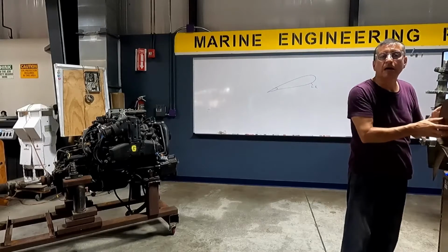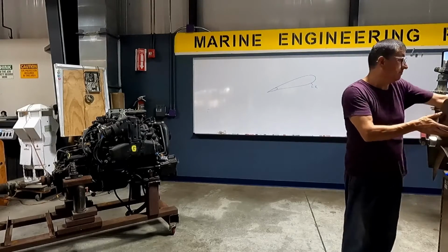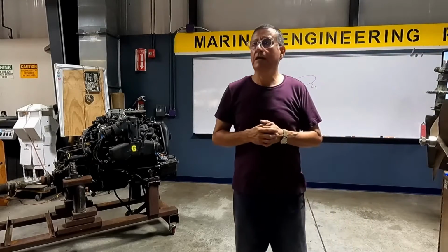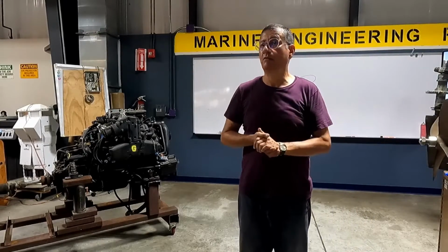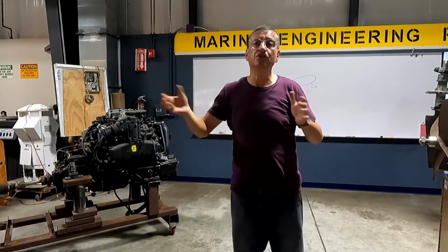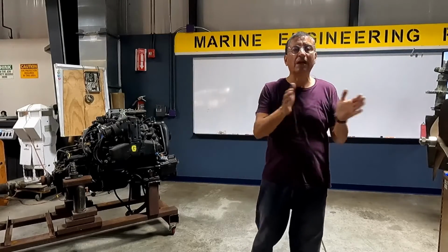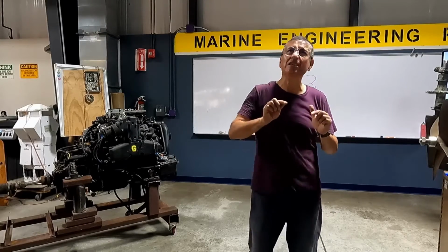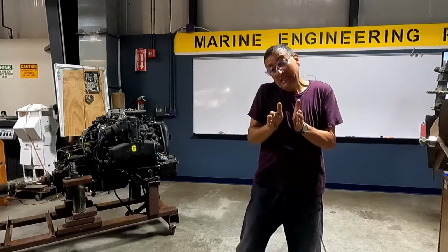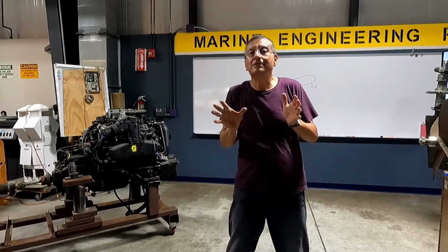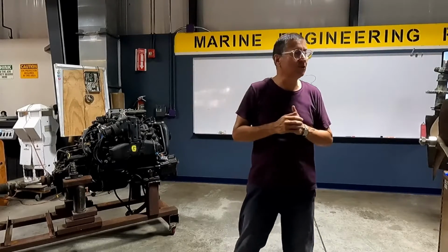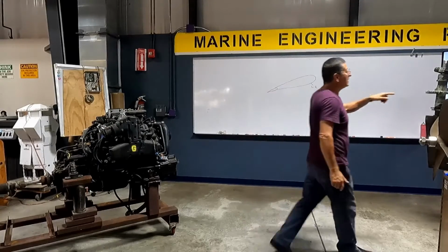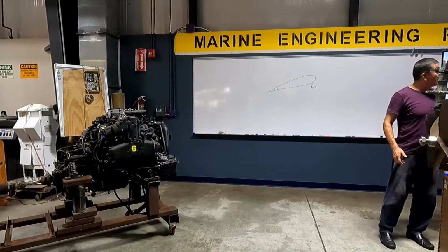Barnacles, a lot of barnacles in the propeller, and barnacles on the shaft, especially on the propeller, produce vibration. And this is a typical complaint of the captains. Vibration in some RPMs, in some range of RPMs. It's in the range where the harmonic distortion is maximum. In the other frequency is less harmonic distortion. Right? Okay. Other important thing is about the pitch and the diameter.